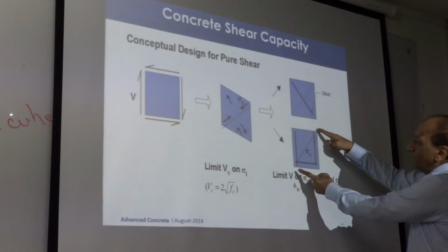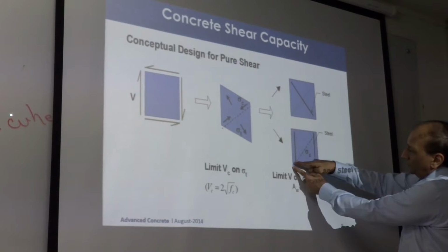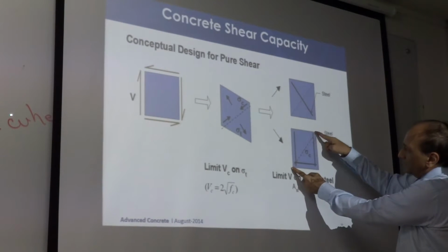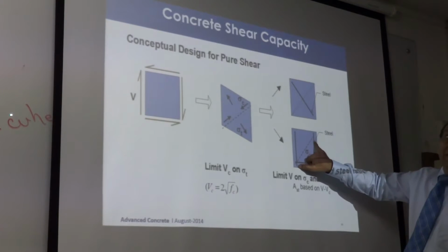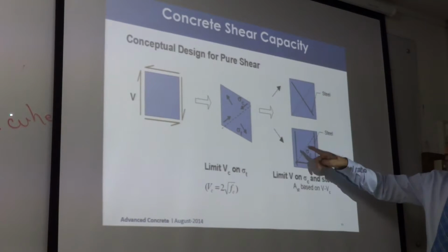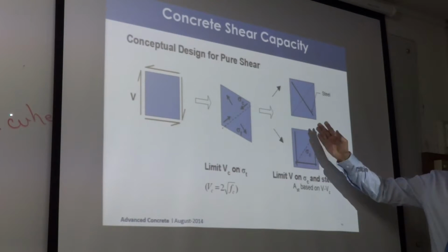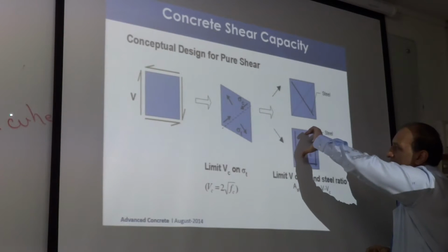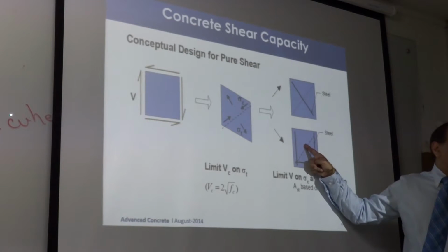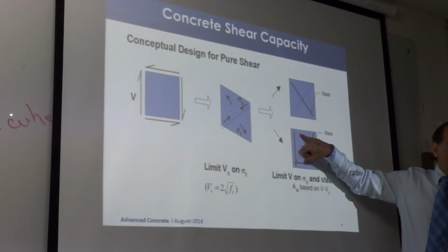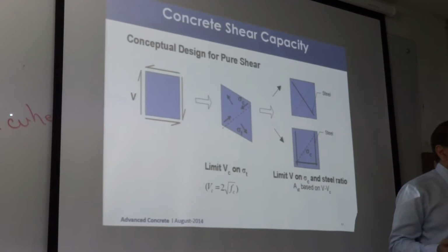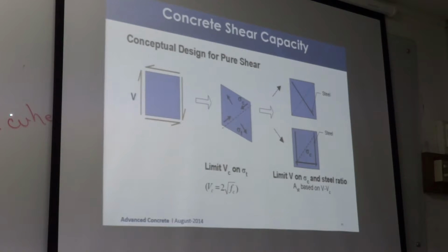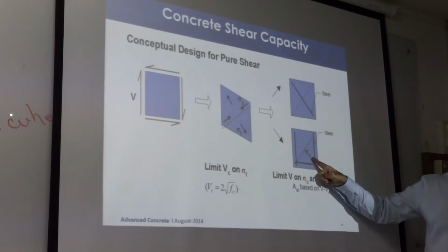We calculate what is the total tension stress here, multiplied by this length, which will be the total force. Then you calculate the required reinforcement, take the component, and then you design. In fact, if you take this length as the vertical length instead of the diagonal length, it is already the component, so you don't need to take the component.